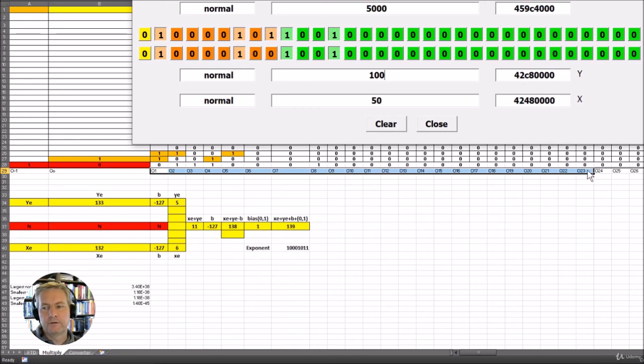But what matters is that the next bit after the 23rd bit is going to be the guard bit. And of course we're interested in the guard bit, and we're interested in the other 22 bits which are beyond the guard bit. So in this instance, it's going to be from the position here, output 25, which is this point here, and we're going to have the 22 bits afterwards. Those 22 bits are going to be ORed together in order to give us our sticky bit.